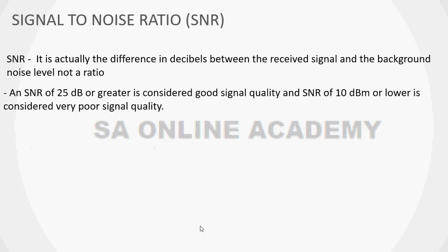So an SNR of 20 decibel or greater is considered good quality, and an SNR of 10 decibel or lower is considered very poor signal quality. So while designing your solution, do remember that you should keep an SNR of 20 decibel.